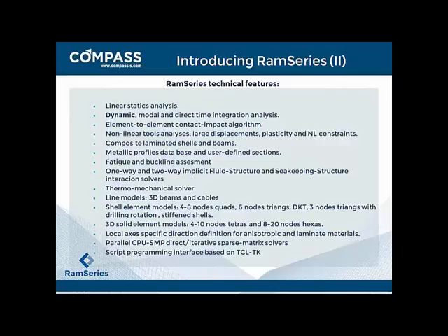Regarding the technical features, linear static analysis is available, and dynamic analysis, which encompasses modal, frequency domain analysis, and direct time integration, which is what we are going to see today. Element-to-element contact impact algorithms are also available, and as I mentioned before, nonlinear solvers for large displacement.